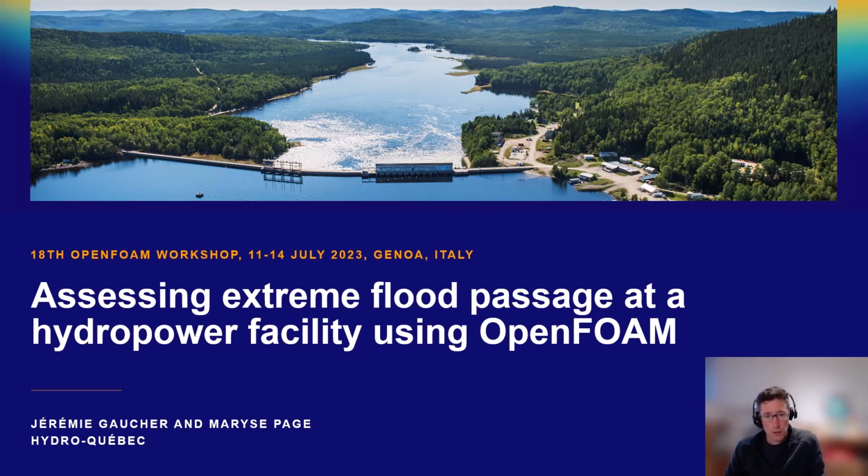The topic of my presentation today is about application of OpenFOAM to dam safety. I'll present you a recent project in which we used OpenFOAM to verify the safe passage of various flood events through a hydropower facility, through its spillways, and how we used it to evaluate the water levels.